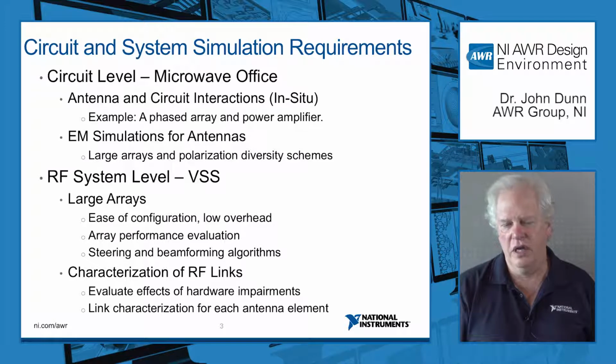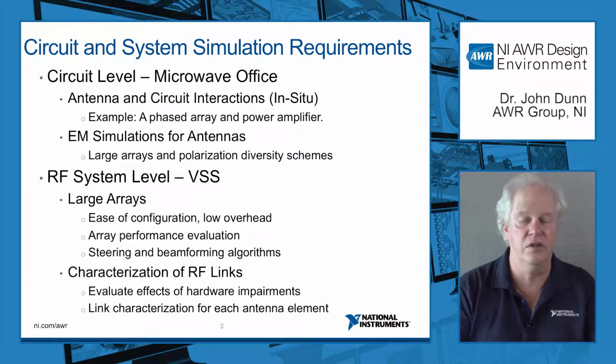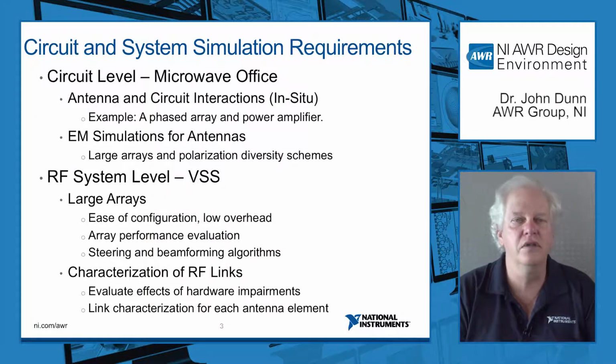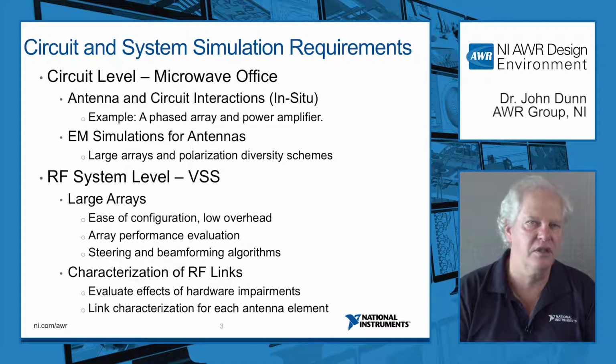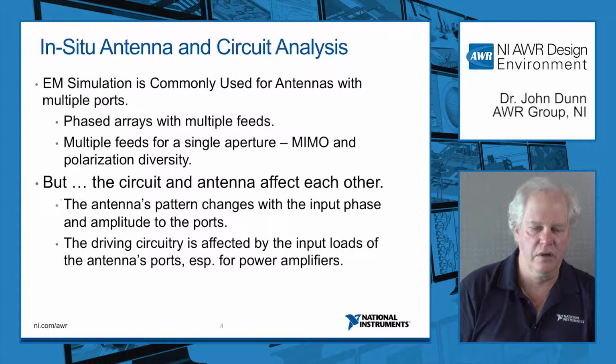Another thing I want to show you today is at the system level, and in particular in our system simulator, VSS, Visual System Simulator. Again, you probably want to include array effects, and we have a new element in VSS, which is an array element. It basically uses the array equations, and it has a number of nice features to it, which I'll be getting into. Once you have this element, you of course can look at the array effects, you can look at propagation effects, etc. So we're going to take a look at both of these guys today and see how they work. All right, let's get going with the antenna.